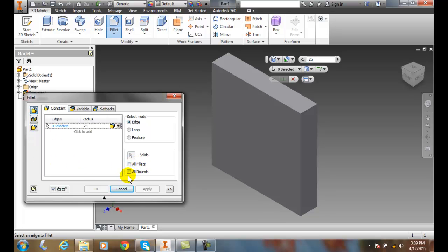This is a very easy way of putting fillets in, and typically we put fillets in to prevent stress in those areas, and so that people don't get cut mishandling products. They could get their hands cut by too sharp edges. So fillets are usually for those two features.